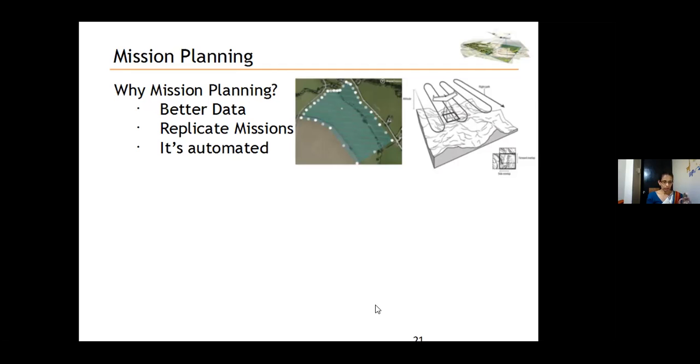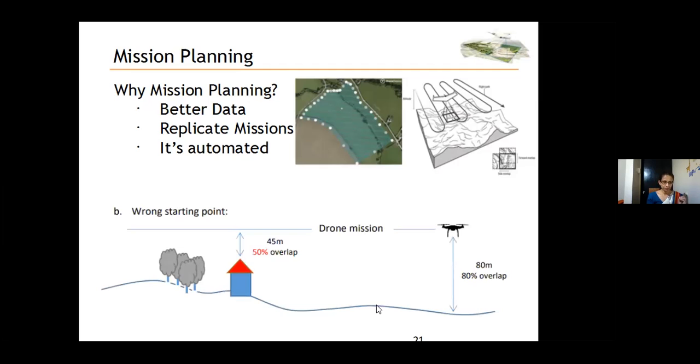Also, we know a lot of problems are caused by poor mission planning. Photogrammetric missions must be carefully planned and executed according to the flight plan to obtain the required accuracy and completeness of the project. Failure to obtain satisfactory photography during a flight mission or to create the right flight plan is not only an economic loss in terms of time and resources, but in all probability will also damage the UAV.